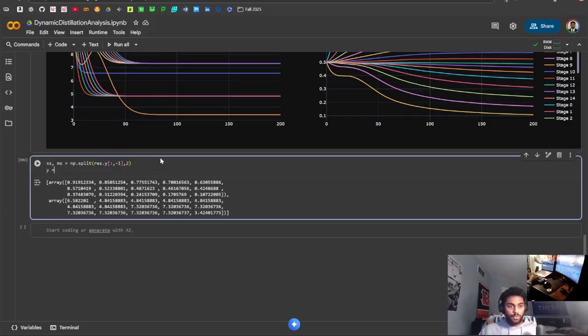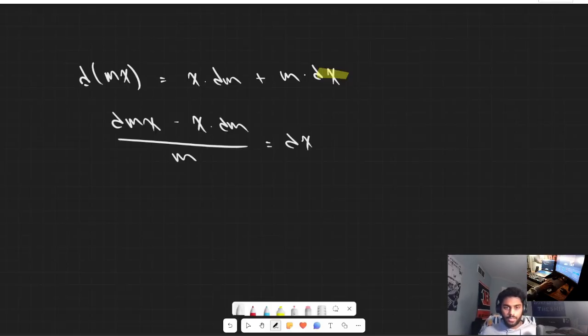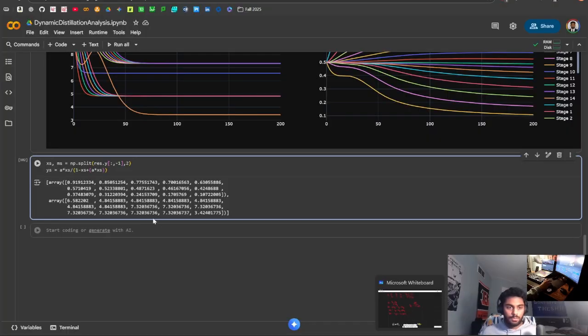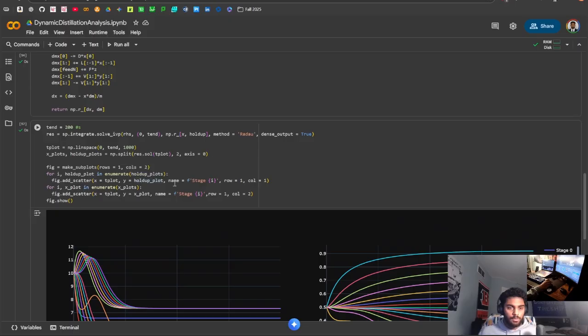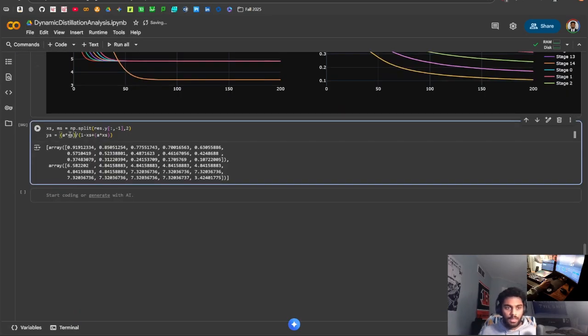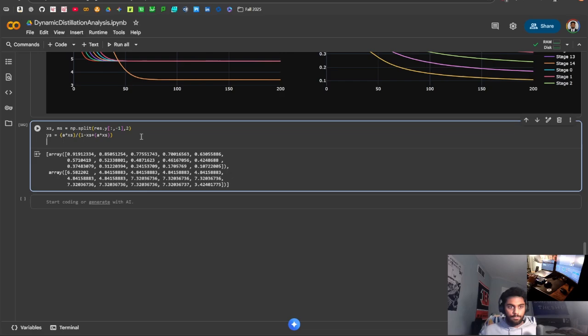Based on those x's, we can get our y's, and that is going to be, well, actually that exactly, that's our relative volatility. I believe it should be, or let me double check myself. Yeah, alpha x. So alpha times x. Did I do that up here? Where's my y's? Yeah, so alpha times x over 1 minus x plus alpha times x. So we have our y's.